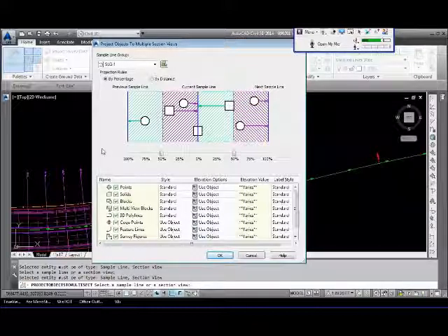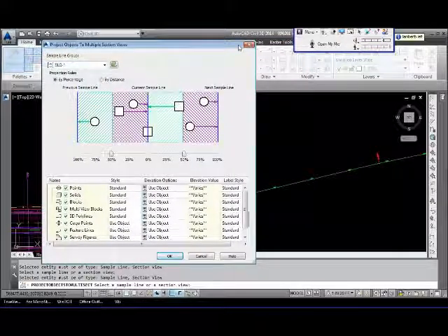So the critical thing here is, if you're working with an alignment object or a 2D polyline or even a line, you've got to get that converted to a type of object that can be represented in 3D. That's one of the requirements of this method. So just to be aware. Thanks, Eric, for the little input.